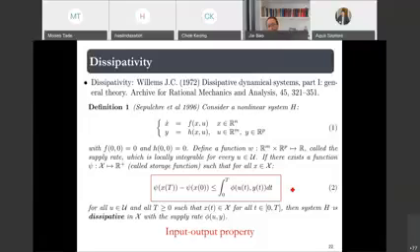We see whether we can find a Lyapunov function which is positive definite, and if we can show that its derivative with respect to time is less than 0 when x travels on the trajectory of the system, then we say that the equilibrium point is stable.